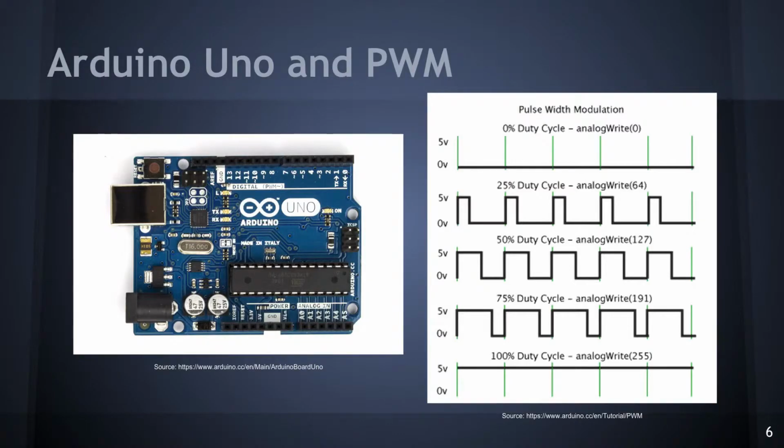Before we talk about the specific details of our project, I'm going to go into some of the major components that make it up. One of the things we used was the Arduino Uno, which is a microcontroller board. This board has 6 analog input pins, each of which are connected to an ADC, or an analog to digital converter. Each ADC has 10-bit resolution, which means that an increase in 1 in a binary output of the ADC corresponds to an increase in 4.9 millivolts on the analog input pin.